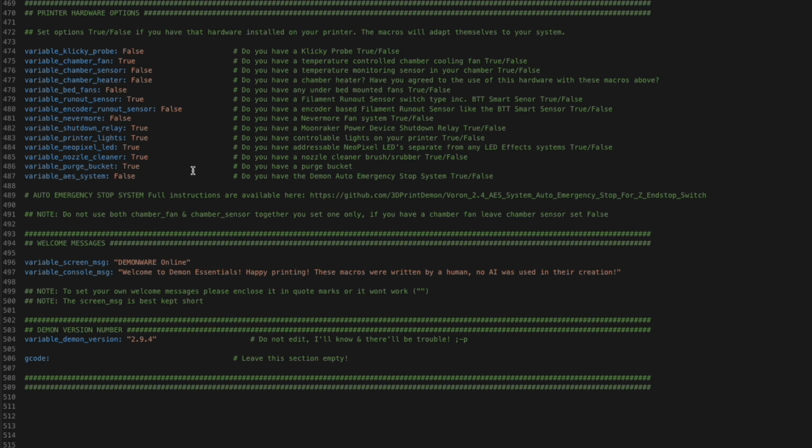It's an automated emergency stop system that will shut the printer down if it senses that the printer has missed the Z end stop switch for any reason, and the nozzle is going lower than the activation point of the switch during the homing process of the Z-axis.